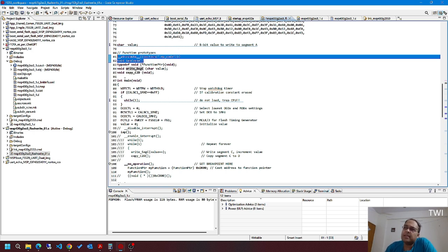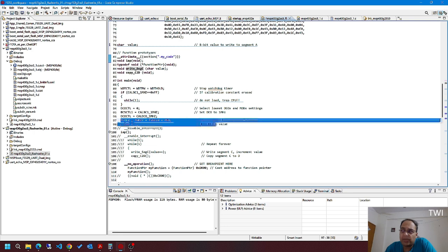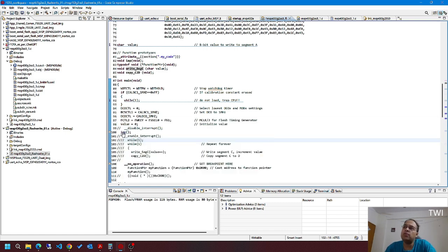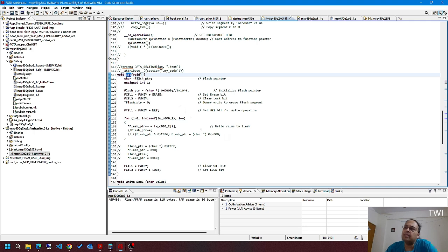It's basically a simple code that starts with configuration of the clock, and then it opens the flash memory and configures the flash timing generator, which means that the flash programmer module has some parameters that need to be configured. So that is done over here. After that, we directly go into the IAP. Inside IAP, a simple flash pointer is declared and initialized to the memory area, as I told you, D000, from where we want our codes to be executed.